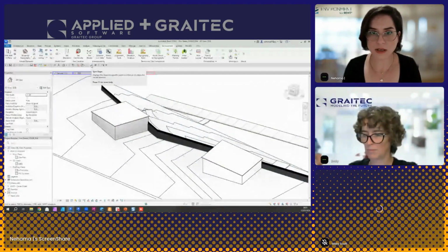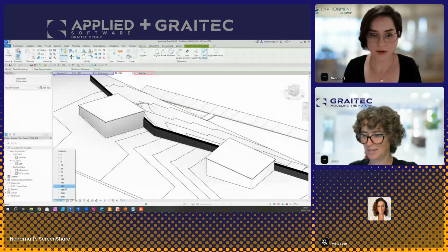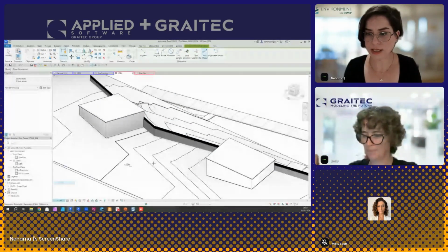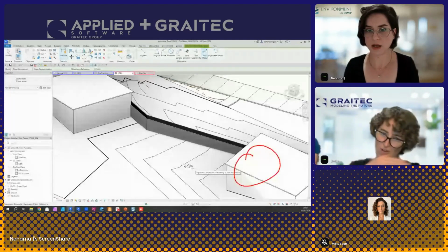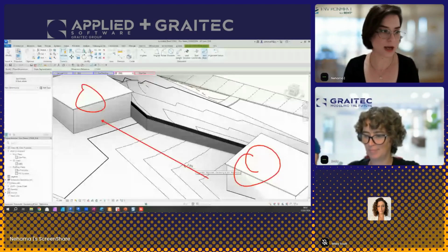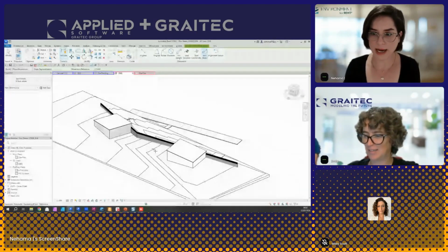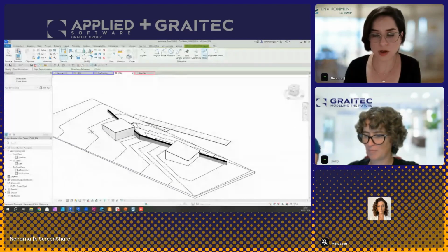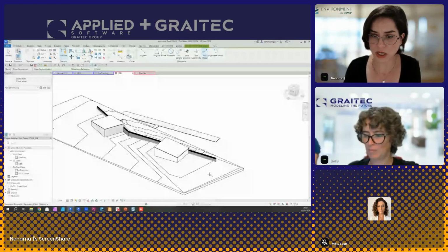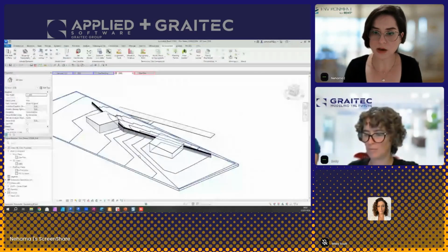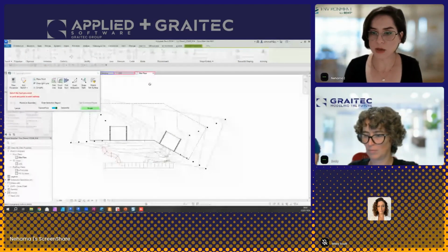If I'm going to use Revit's spot slope tool to get an idea of what my slopes are, you can already see that all my water is going from this building to this building. And this guy is not going to be happy when it rains, right? So I have to do something about it. And I wouldn't even know it. I mean, I would know it as a landscape architect, but using these tools is just another way for me to understand what's going on over here. So let's select this TopoSolid, go back to the topography tools and see what I can do with it.